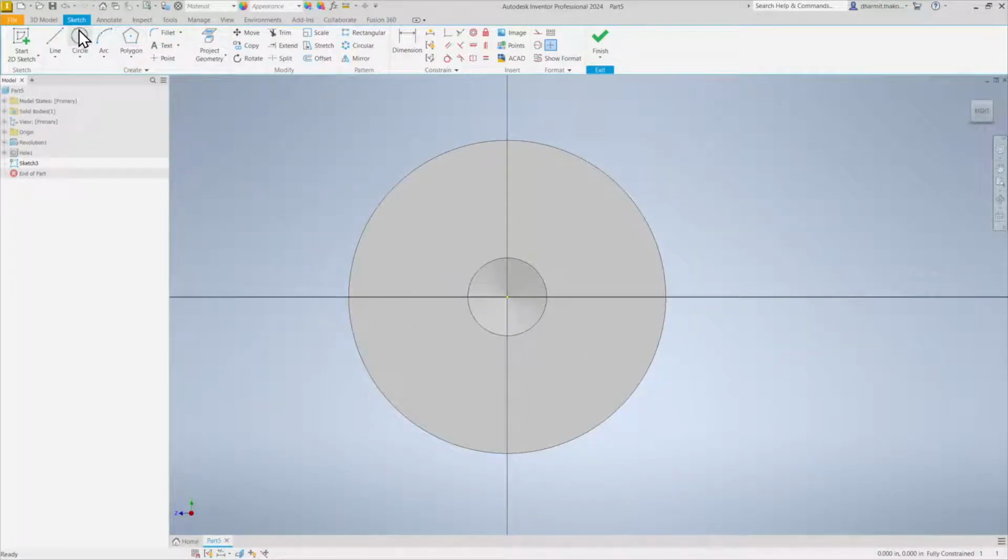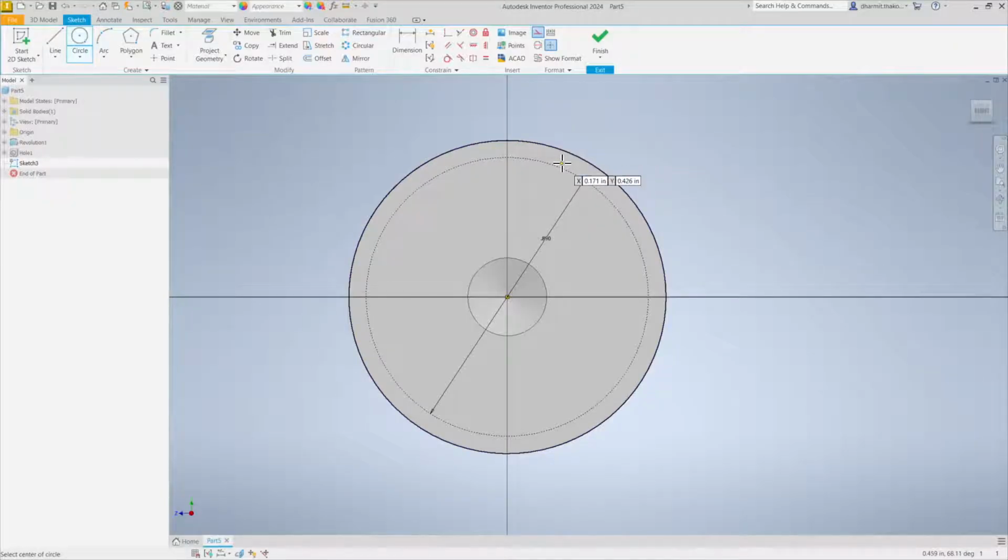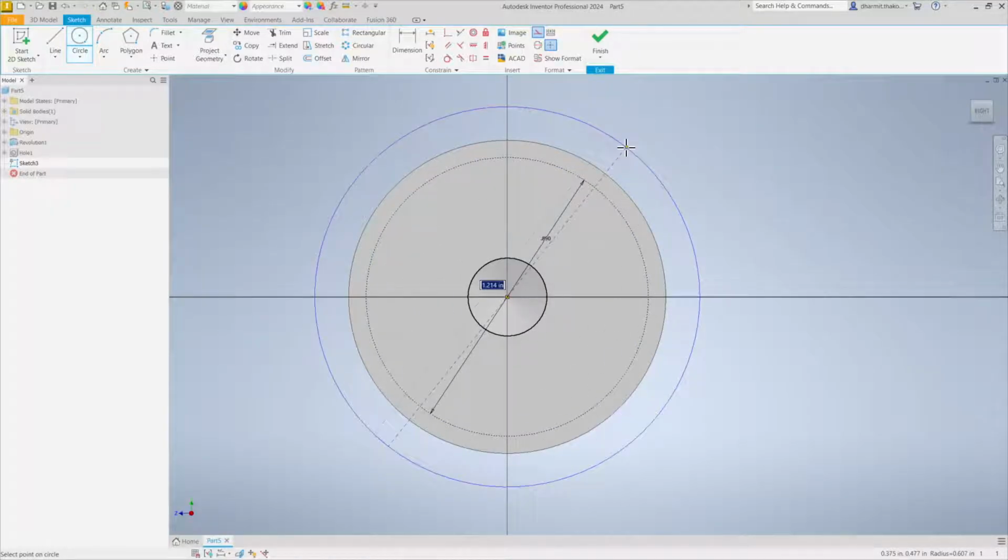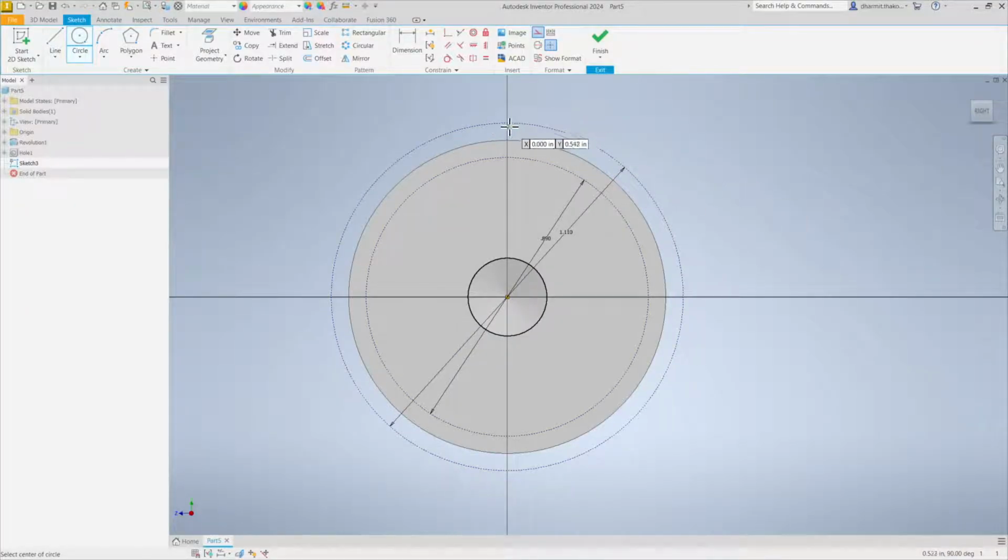and then for the inside, I'll click on construction line. The inside diameter is 0.89, and the outside diameter is 1 inch. The difference here is 0.11. So I'll create another circle which is 1.11, so you can create your lobes in between these 2 points.